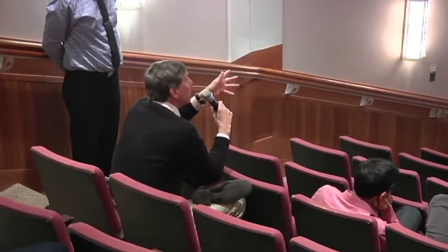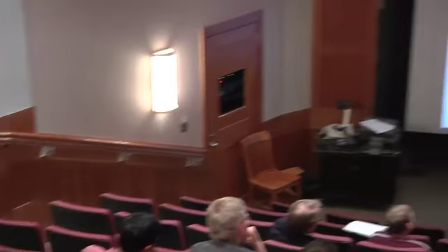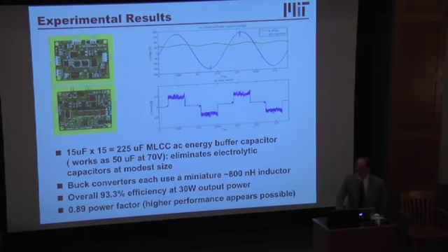Related question. What's the sign of the power factor typically? Is it inductive-like or capacitive-like? In the ones we've built, it's almost resistive. It's mostly distortion factor. Are you asking of the commercial power supplies? Yeah, let's say typically it's somewhere between 0.5 and 0.7 or something like that. Yeah, mostly those are distortion factor.